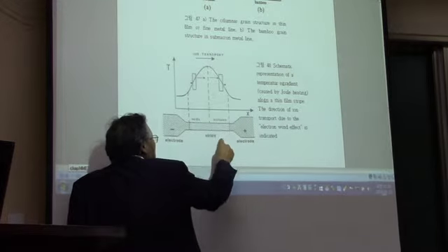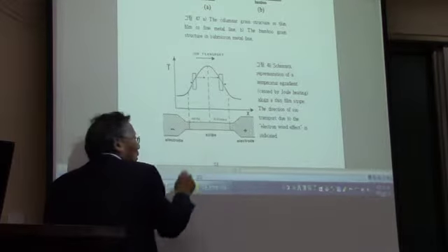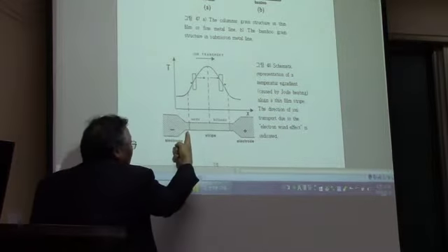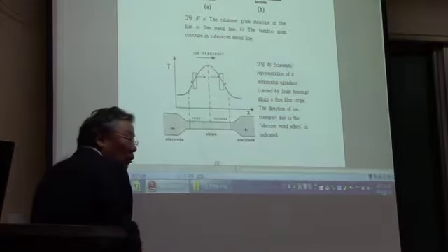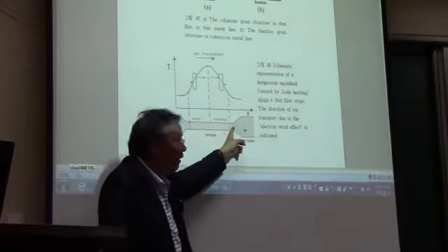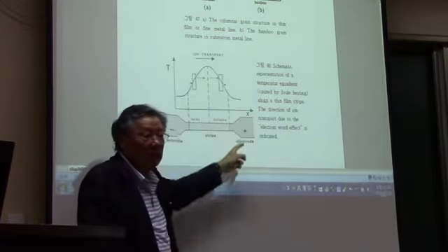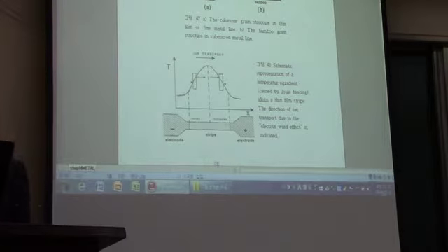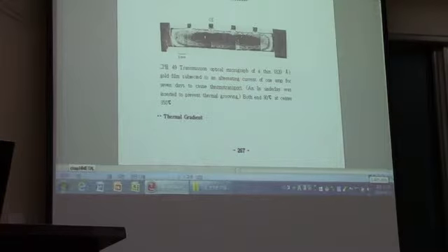So at this part, you're going to have a hillock, while at this part, you are going to have a void. So you're going to have a necking phenomenon. You're going to have a failure at this neck, okay? And you're going to have hillocks, a lot of rough surfaces at this end. And we call that thermal migration. And this is the typical example. It's a simple example, but very powerful, very clever.